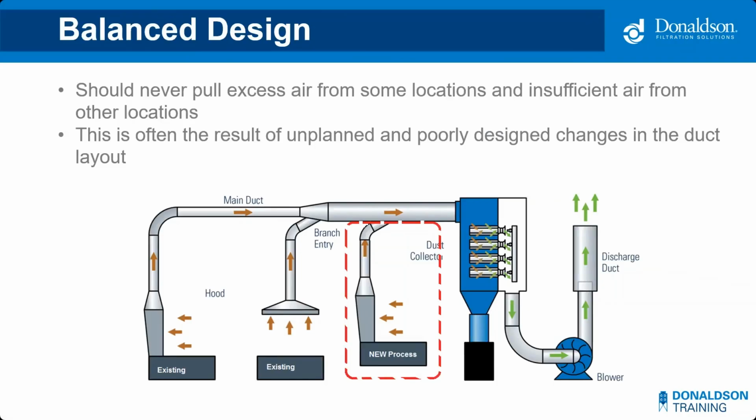It's pretty common that we see customers have added new drops to an existing system without considering the impact it has on existing equipment. If you remember way back in the beginning, when we showed the overall system, I said that they're designed systems. If one part or one component is poorly designed, it affects everything. That's the most common thing we see: somebody adds a leg after the fact without knowing that the system wasn't designed to handle another leg.